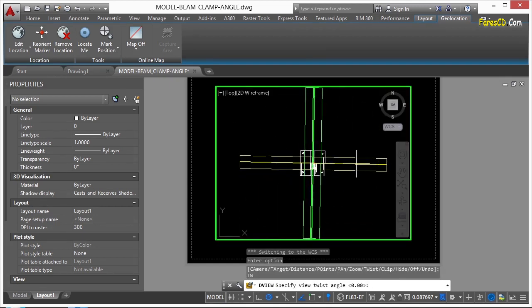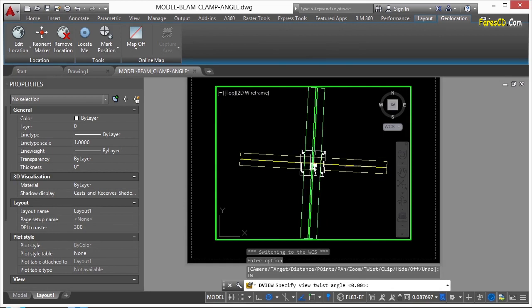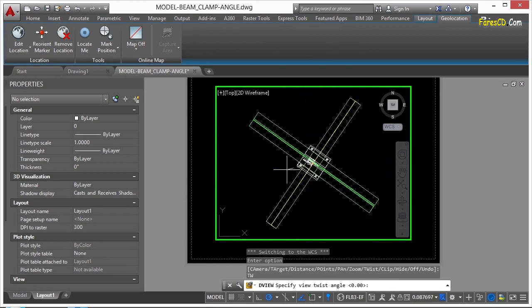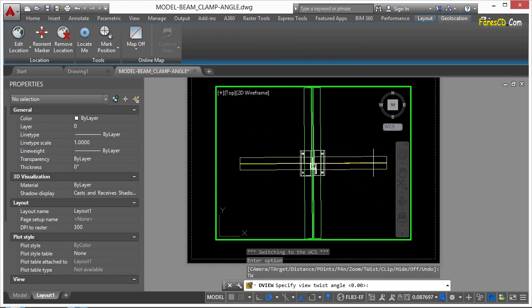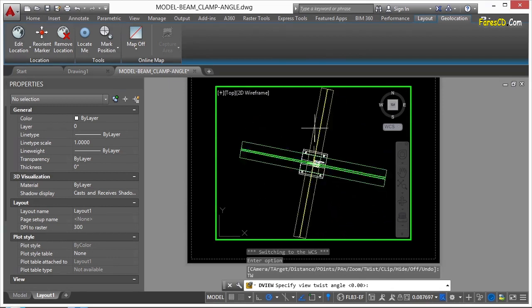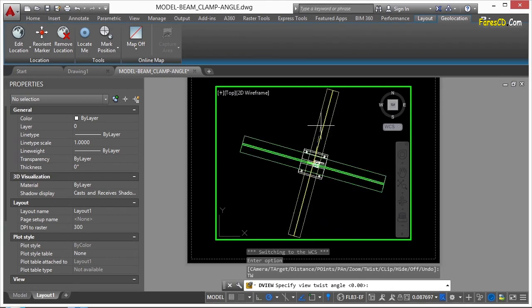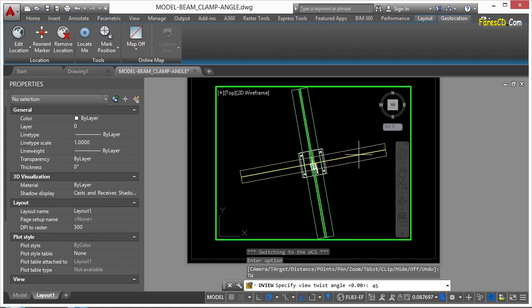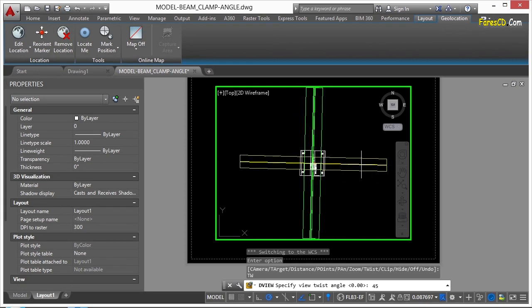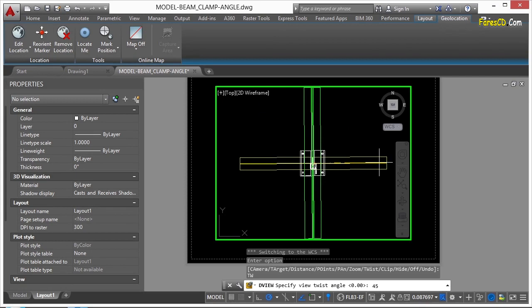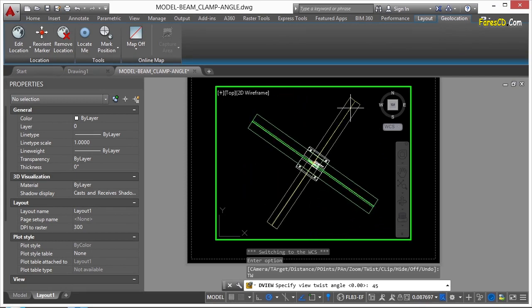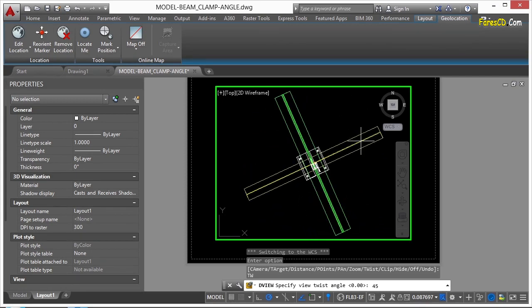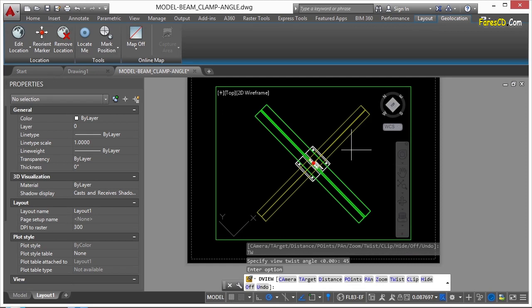Now it starts off just like AutoCAD's rotate command. This is at the perfectly horizontal option. That's at 0 degrees. Now I can tell it where to rotate just by moving my mouse and clicking, or I can type in a command or an angle. I'm going to type in 45, so it makes it very easy for you to see. So it's going to rotate from here in this horizontal position on the right side of my screen up 45 degrees. So it's going to put it right about there. So I'm going to press enter, and that's my view.